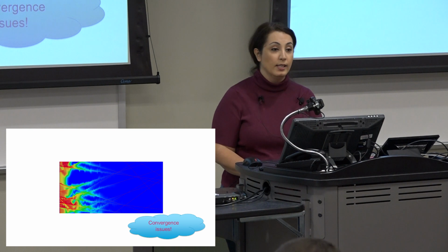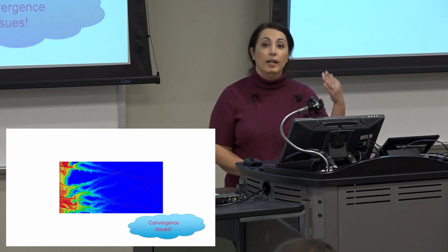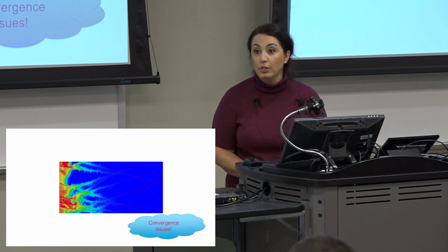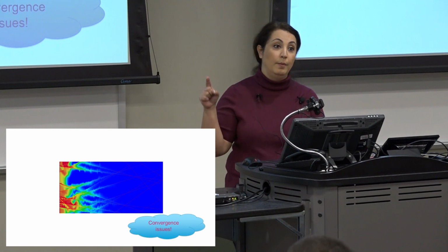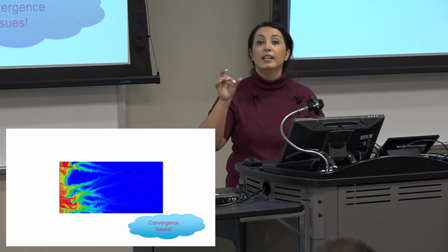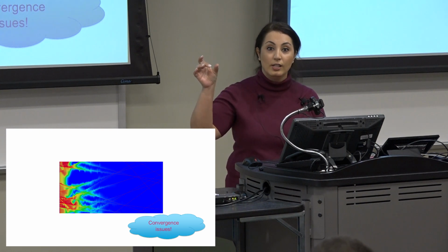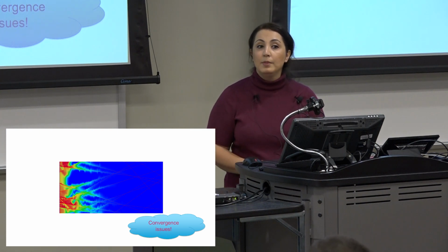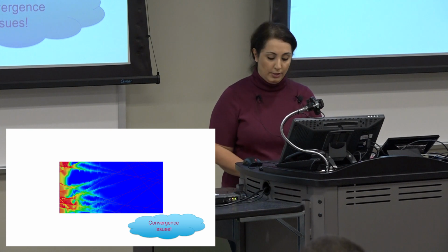Why is that the case? Because behind the scenes, we are using the advection dispersion equation, and the velocity term in some locations is so high that my time step cannot keep up with that high velocity. Even with an adaptive time step, it doesn't converge.